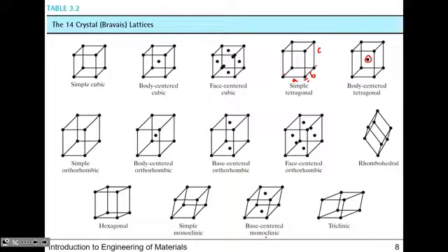Certainly in real life materials, you can start with, say, nickel FCC, copper FCC, aluminum, these are common materials. You can start off with that, but in real life, there's always a point defect, right? You could very well and will definitely have missing point defects, where you're missing an atom there, so you could have a vacancy. But overall, in these systems, you would still say it's FCC and identify a point defect. But you still have that FCC symmetry, all right, face-centered cubic symmetry.